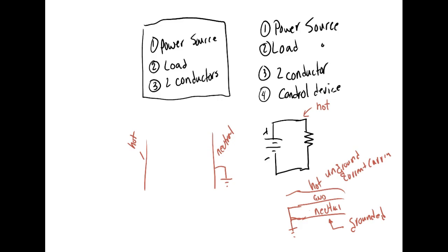That makes sense? You understand? So we're not doing this. We don't have a neutral. L1 is considered the hot side and L2 is considered the common side, because ground does not come through the transformer. Y'all understand that? So you literally have to ground the secondary of the transformer. That's why your house has a ground over there by your box, because they ground the neutral at the transformer.